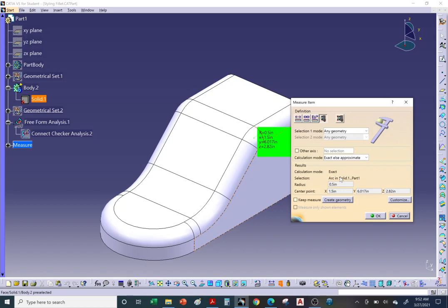Okay, so here's one of the rules. When you create the tube, you're going to make it slightly larger. Instead of a tube that intersects just in this area here, we're actually going to go slightly beyond, about 20% if I remember correctly.